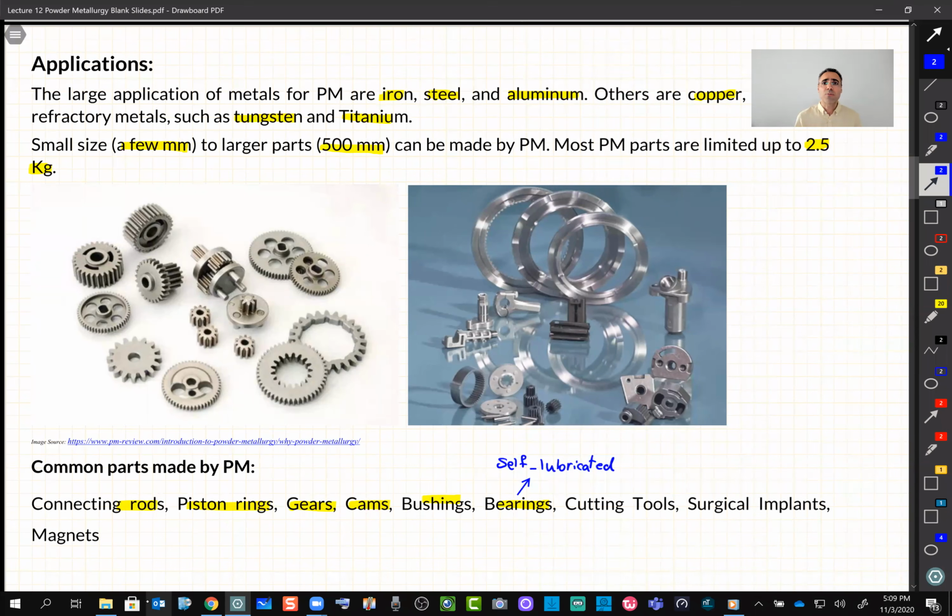So the mold has to be made out of a material which has an even higher temperature, and again, making that is not impossible, but it's very difficult. But using powder metallurgy makes it possible. So cutting tools very commonly use this approach.